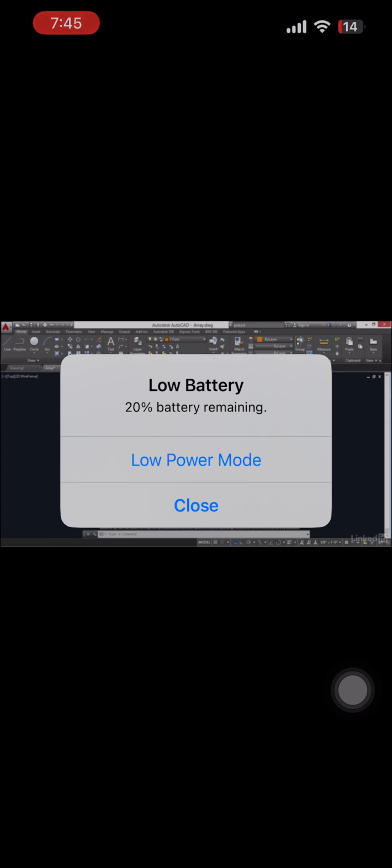Now position the cursor over one of these chairs and you'll see that it's all one thing. It's an array. If I click on that, I can then go back here and edit these values. Close Array. Now let's say that I want to have a room of these training desks, so we can make an array of the array. Go up here and choose Rectangular Array again, and this time select the array and the table.